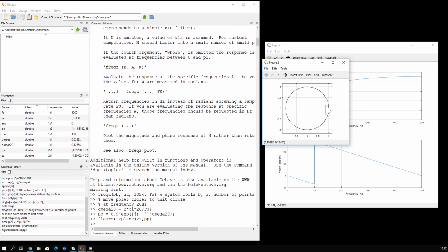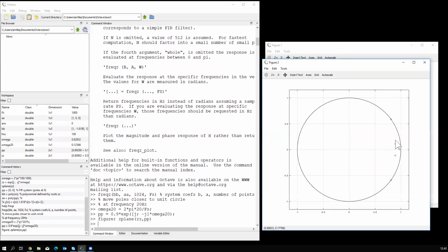Since this is about 0.1 at this point, or maybe I should make it a little bit bigger, in case you have a smaller screen. So the distance here is 0.1. This seems to be about 0.2. So on the denominator, we now have a gain of 10 and 5. So it's 50 times gain in that region.